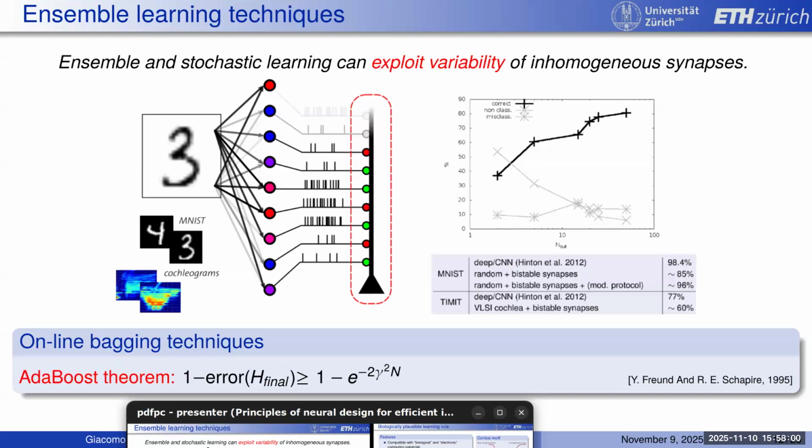There is no amplifier, so if there is no spikes, there is no current flowing, there is no power being burned. So that's the nice thing about these chips. If you have biosignals that are quite static for seconds, nothing is burned, and only when you have a peak coming in, if you encode it with a sigma delta, then you see something change, and then you charge up a capacitor, and then the power itself is just the capacitor discharging. There is no static power being burnt at all. Imagine if you have a GPU or a microcontroller, you have a clock running all the time, whether you have data or not, you keep on doing cycles and burning power.